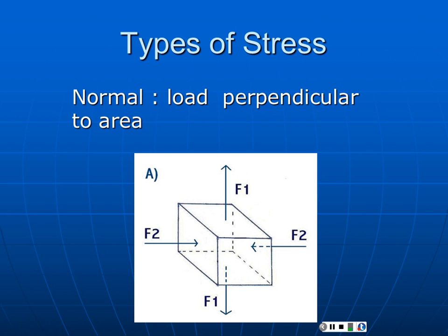So signs and forces have to do with sense, not direction. Forces will have a positive sign for tension, a negative sign for compression, and so will stress. The stresses that result from those will be positive or negative based on tension or compression.